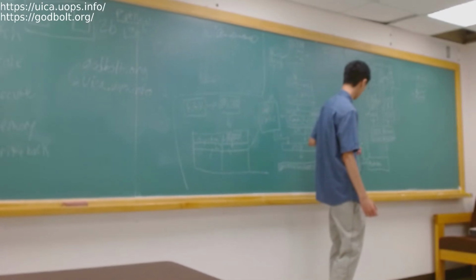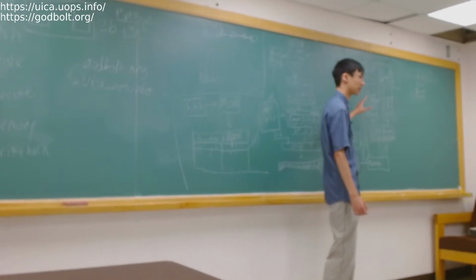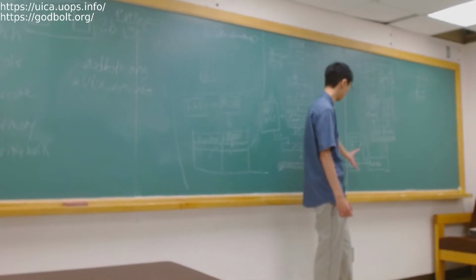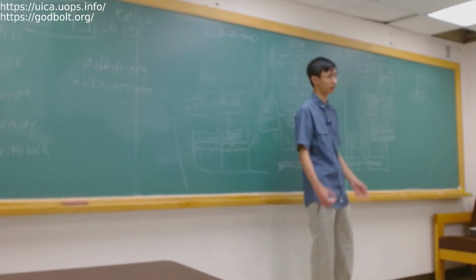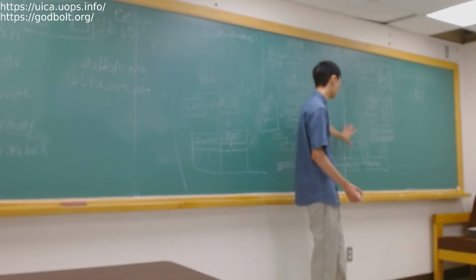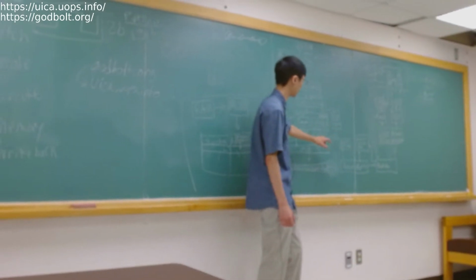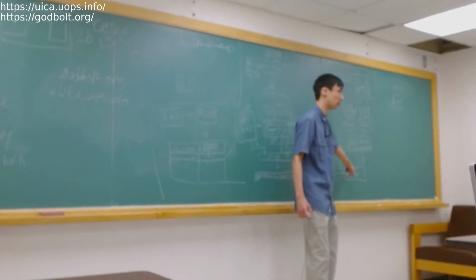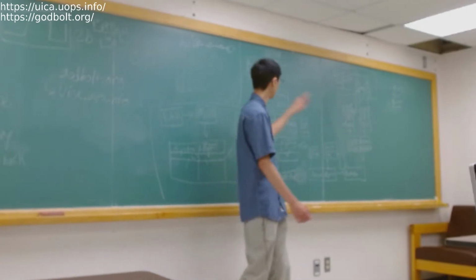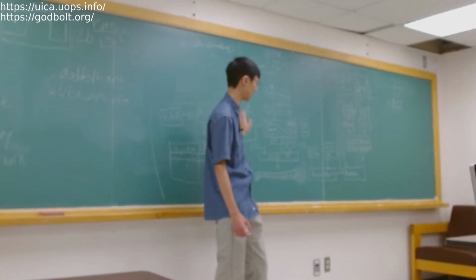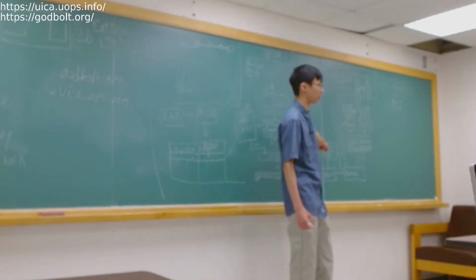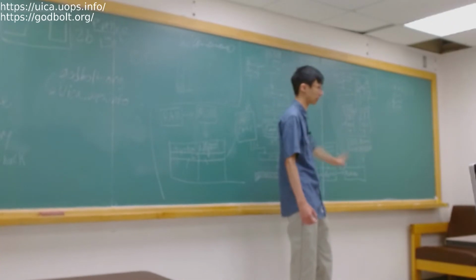Right. So yeah, and then this part becomes less interesting for you guys because most of the time you won't fill out all of this information for the rename and register allocation table. I have never seen someone actually bottleneck on that. Well, this one is technically a bottleneck just because the speed you get between rename and reorder is going to be 4 micro operations because the register allocation table can only do 4 renames at a time. And so that means if you have a uops cache pushing in 6 micro operations at a time, then you're going to stall on this register allocation table because you're only going to get 4 through.